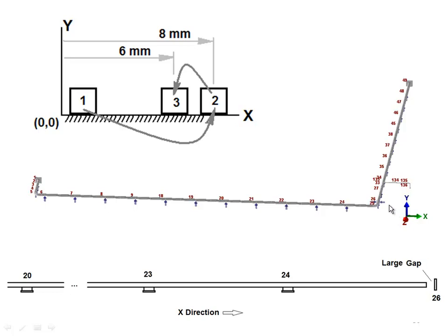This is so far so good for a program that uses total displacement to determine the direction of the friction loads. By the time the gap closes, a good part of the X run of pipe is sliding in the plus X direction through 1 to 2 inches of displacement, and the loads acting on the supports are acting in the plus X direction. When the gap closes at the end of the pipe at node 26, the supports close to 26 continue moving toward 26, but the supports further away, for example at node 20, stop and begin moving in the minus X direction.